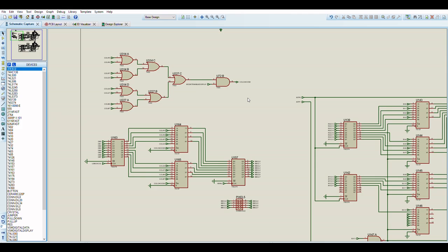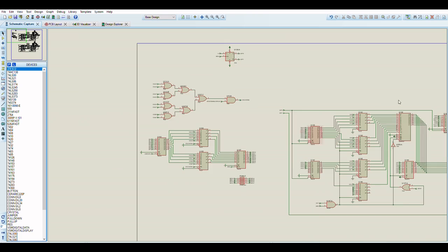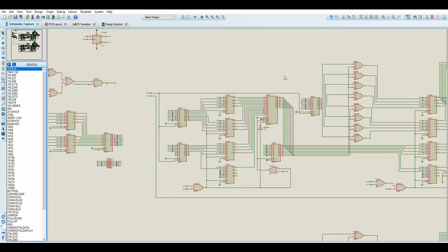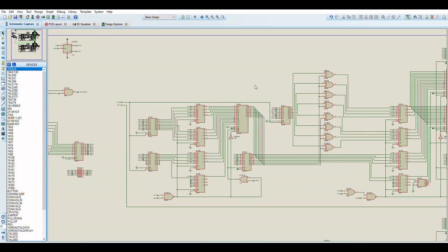I did not want to have bit planes for the mode 7 screen because it would have made the circuitry a lot more difficult. So I sacrificed the number of mode 7 16 by 16 tiles. I sacrificed the number of tiles by reducing the number of tiles, but increasing the number of colors that you could have in the tile.